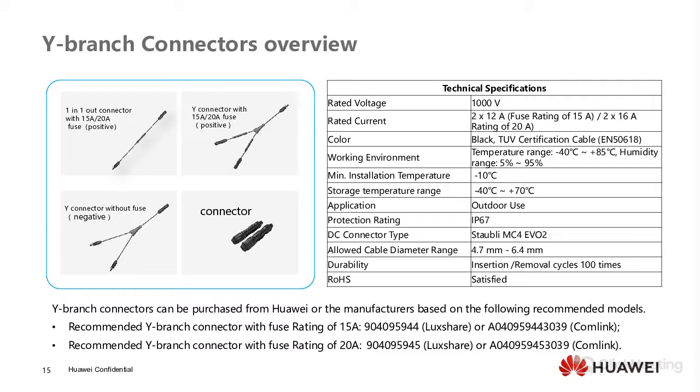Now, these Y connectors, I just need to mention, they do have a fuse protection inside of them because you're going more than 2 strings in parallel per each MPPT. In order to be a safe application and be in accordance to the standards, we will need to ensure a fuse protector is incorporated within that particular MPPT. So these are the specifications.